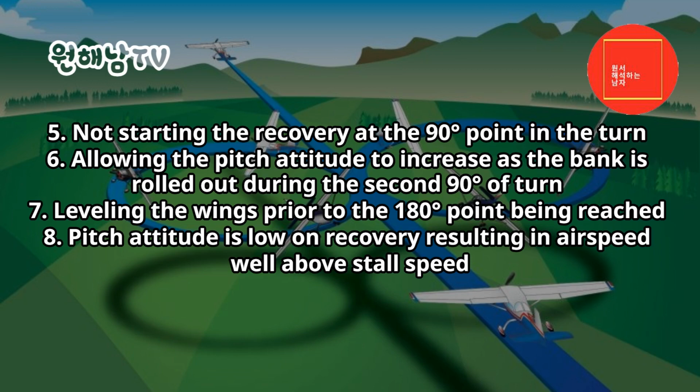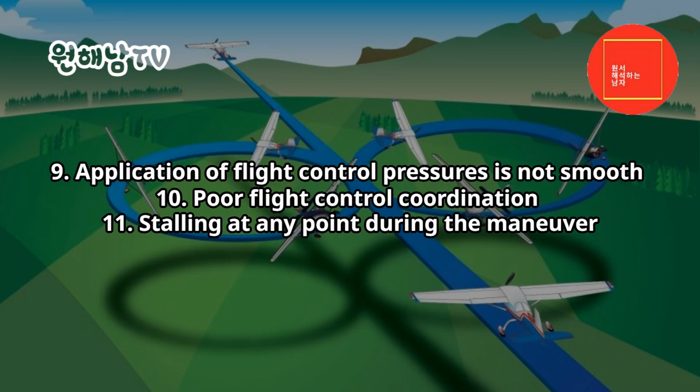7. Leveling the wings prior to the 180 degrees point being reached. 8. Pitch attitude is low on recovery, resulting in airspeed well above stall speed. 9. Application of flight control pressures is not smooth. 10. Poor flight control coordination. 11. Stalling at any point during the maneuver.